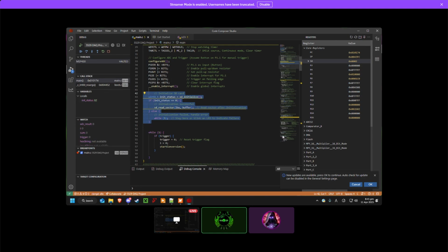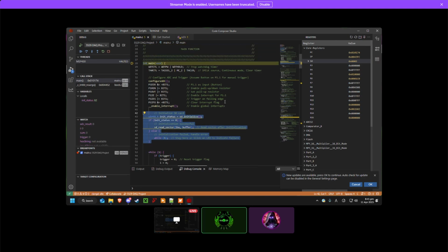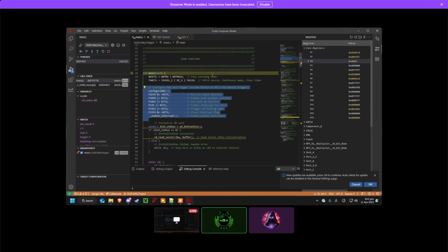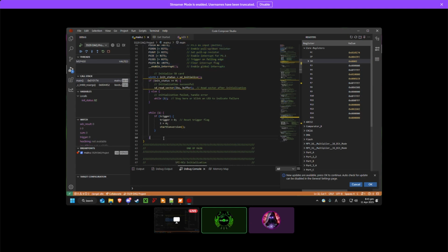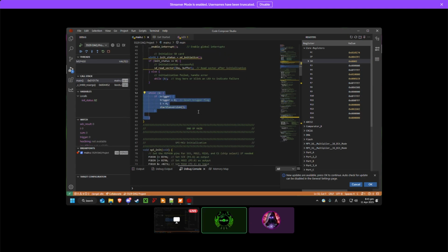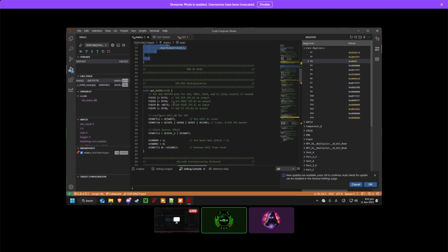This was added. This is for the micro SD card initializations, SPI initializations. We're not working with this right now. So this is just the ADC trigger setup. This is the button 1.1 for the ADC trigger. That allows you to hit the button. We are polling for that trigger. Polling, that's P-O-L-L. And we are waiting for the button to tell it when it is 1.